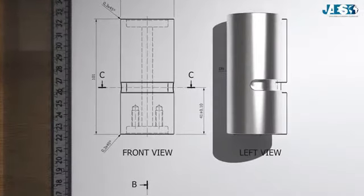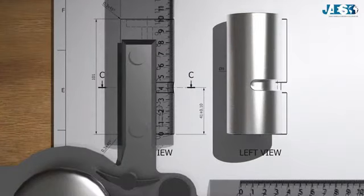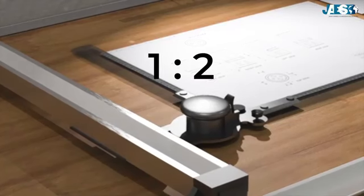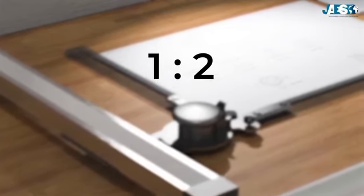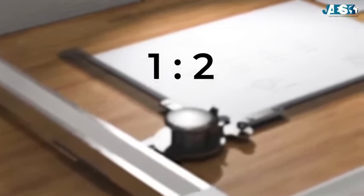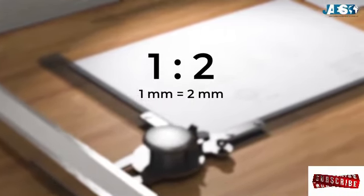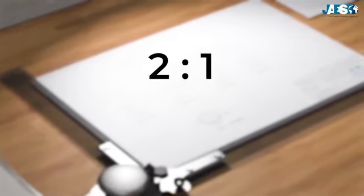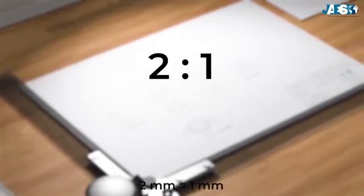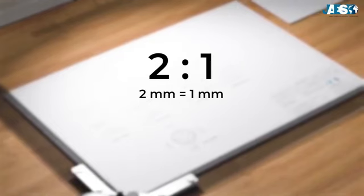So if we take measurements directly from the sheet by means of a ruler, these will be effective. While if it is written, for example, scale 1:2, it means that the object is drawn reduced by half of the real size. In practice, the dimensions we measure will have to be multiplied by 2 to understand how big it really is. On the other hand, if it is written 2:1, we are dealing with an enlargement. The object would be drawn twice as large as it really is, so we have to divide the measured measurements by 2.